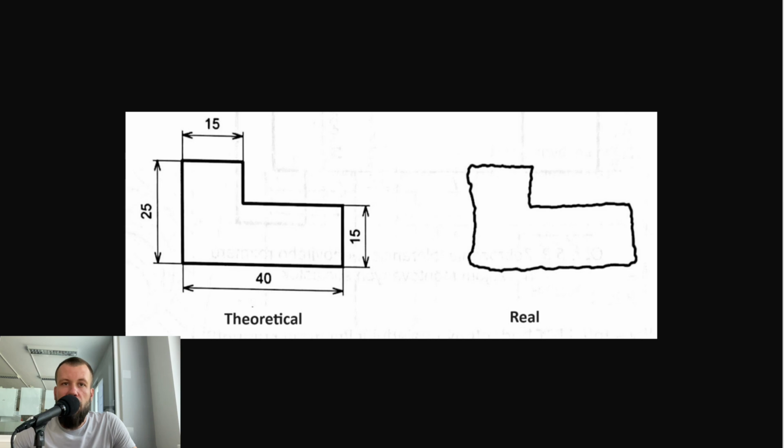Even though man is a perfect creator, in engineering manufacturing he has not yet been able to manufacture and measure any objects absolutely accurately. Actual surfaces and objects, parts and the like differ in size, shape and position from the ideal surface, as you can see in this picture. This difference is due, for example, to the inaccuracy of production machines and jigs, to deformation and chatter of the workpiece, tool and machine tool, to unevenness and internal tension in the material.